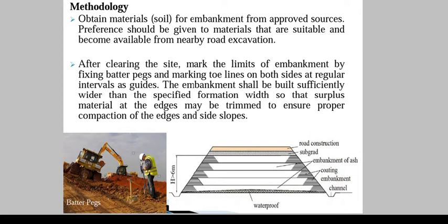To reduce the possible damage to the pavement layer due to capillary rise, capillary water, there is a need for an embankment. To maintain the design standards of highway with respect to the vertical alignment, there is a need for an embankment. Or to have a leveled ground even in the low lying areas to maintain the alignment, there is a need for embankment.